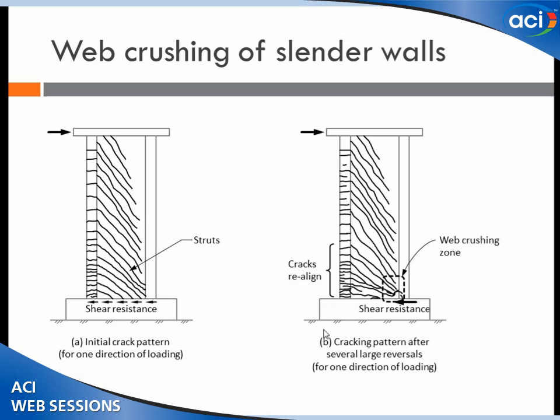There's a realignment of the, let's call them shear cracks, and a buildup or an accumulation of shear that occurs in the web near the flexural compression zone. And this buildup can lead to what's known as web crushing.